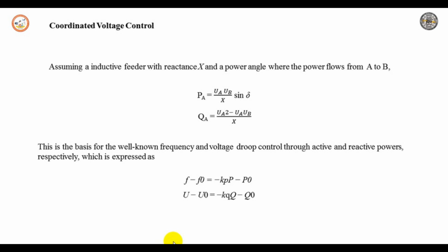So the constants Kp, Kq determine the amount of active and reactive power that is to be injected or consumed at a connection point. They actually represent a virtual impedance between the active unit and the grid, which implies that the increase in proximity means a different amount of corrective signals will be injected.